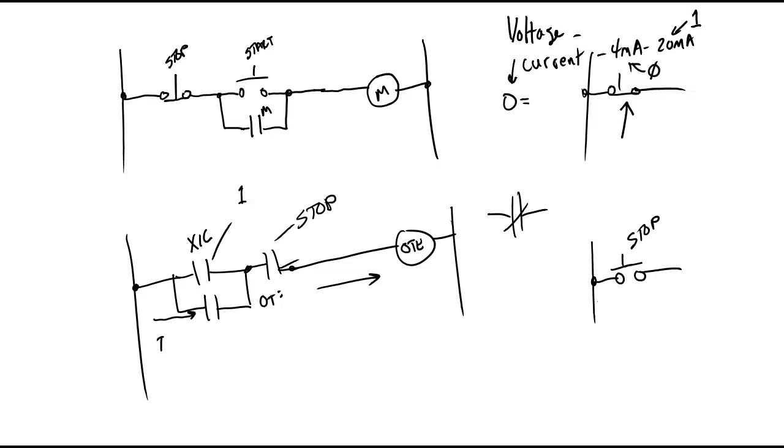And you'll see this in industry, especially with DC motors. They'll use 4 to 20 milliamp. So what would I need for this? Well, I could buy an IO module. I could slap it on the side, and it would do 4 to 20 milliamps, right? So that's the big thing about having these modular PLCs. Normally, by default, they support voltage. Common for analog is 0 to 10 volts. This is pretty standard.